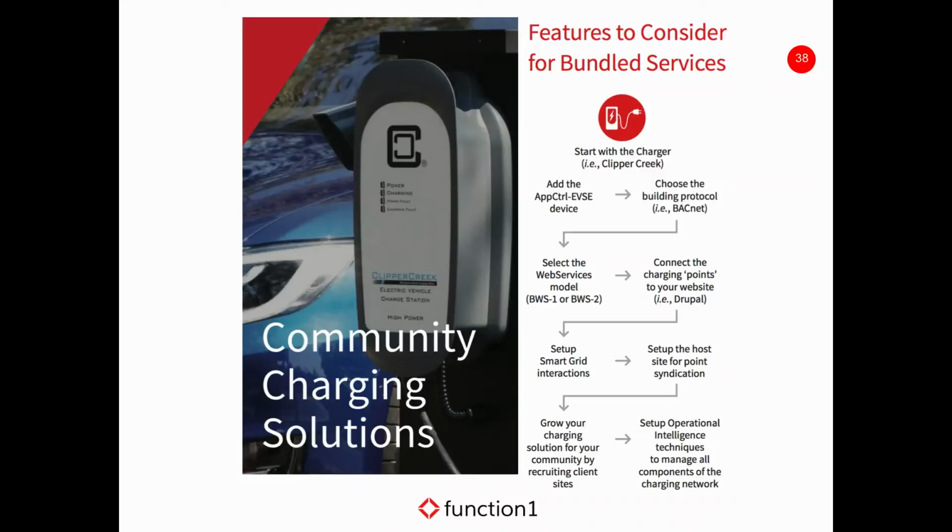But then, the trick is getting the comm line out to wherever this is installed. If this is installed on the side of the building, it's no problem. It's easy to run comm. If it's installed in the parking lot, it might not be a problem, because a lot of times where you have charging stations, you also have lighting and other electrical devices out there for various purposes. So there might be a comm line already going out there. If there's a conduit, we could always just pull another one.